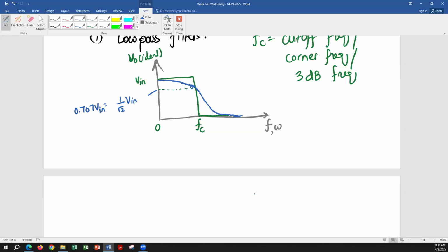Isn't that also the RMS value? The formulation for RMS to peak? Again, for RMS value, you always assume it is for a sinusoidal signal. RMS value for a sinusoidal signal is 1 over square root of 2, that is correct, but RMS value is not 1 over square root of 2 for any signal.